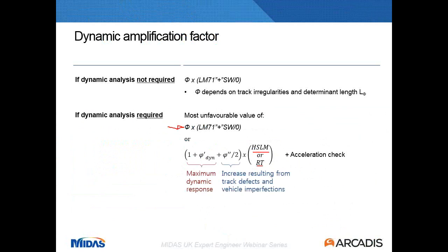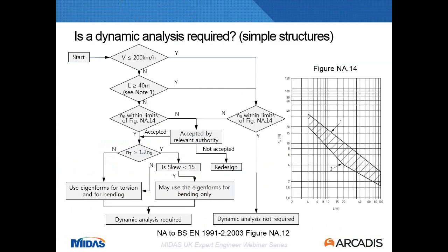So we have these two scenarios, when the dynamic analysis is required and when it's not required, but you might question now, how do I know if I need dynamic analysis? Well, the codes give you a nice flowchart like this one. For the sake of brevity, I'm adding here just one flowchart from the UK annex, and that's the one for simple structures. Simple structures are the ones that behave like a beam element between supports.